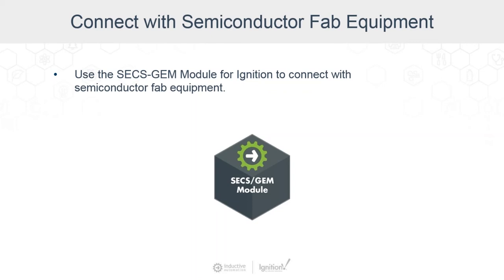Well, yeah, sure. So in an automated fab, this interface, with this protocol, can help you start and stop equipment processing, collect measurement data throughout that, change variables and even select recipes for products. So it really allows you to interface with this equipment for host communication, and it just opens up another channel to more devices, more things that we can work with. So it's very important obviously for semiconductor, very specific to that, but allows you to do quite a bit in that realm.